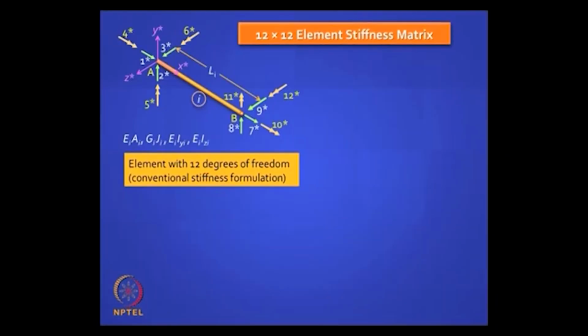Okay, torsional moment, twisting moment, these are words commonly used, and the rotation corresponding to that is called an angle of twist. The rotation corresponding to a bending moment is called simply rotation or flexural rotation or slope, if you wish.